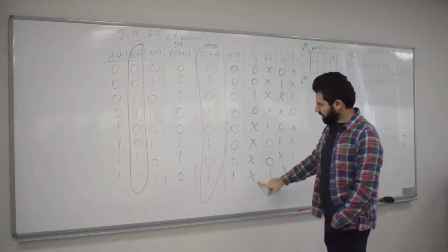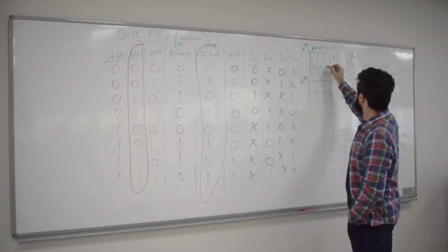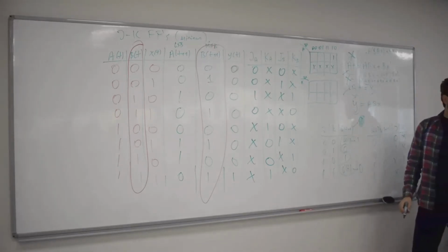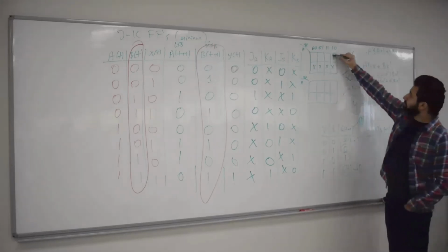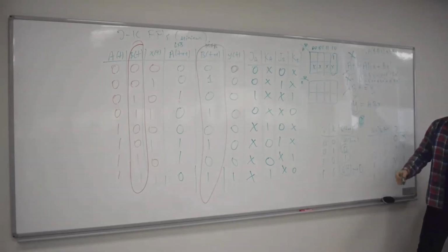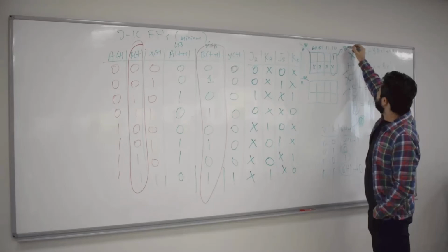And I have 4 don't cares, as you can see, for all A equals 1. Apparently the simplest Boolean expression that corresponds to this Karnaugh map is this. You don't need to consider the rest; just set them to 0, because that would complicate your circuit. So A is gone. You got B X prime.